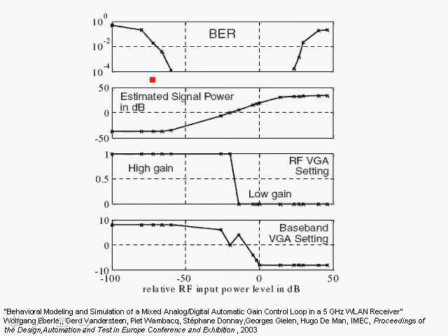As the input signal power increases, the SNR will increase, and there'll be a certain point where we're able to decode the packet and the bit error rate will be very small. During this region, the AGC also kicks in, and we're able to operate over a very wide dynamic range. For example, as we mentioned before, around a dynamic range of 62 dB.